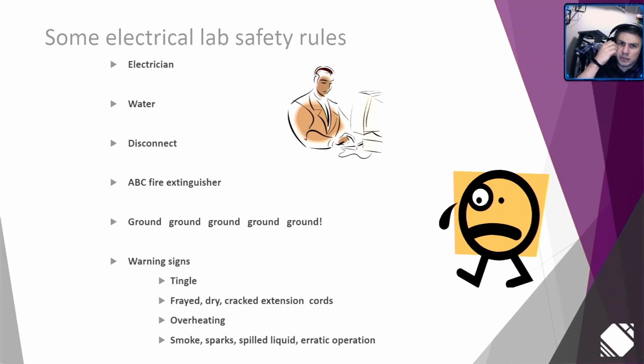At mine sites, because there's a lot more power, we typically have a larger ground grid at the substation, and then that ground is carried forward to make sure that all site is at the same ground potential. At any of the large pieces of equipment, like a large transformer, a large motor control center, switchgear, you'll actually ground both ends of the equipment with two grounds. That way,